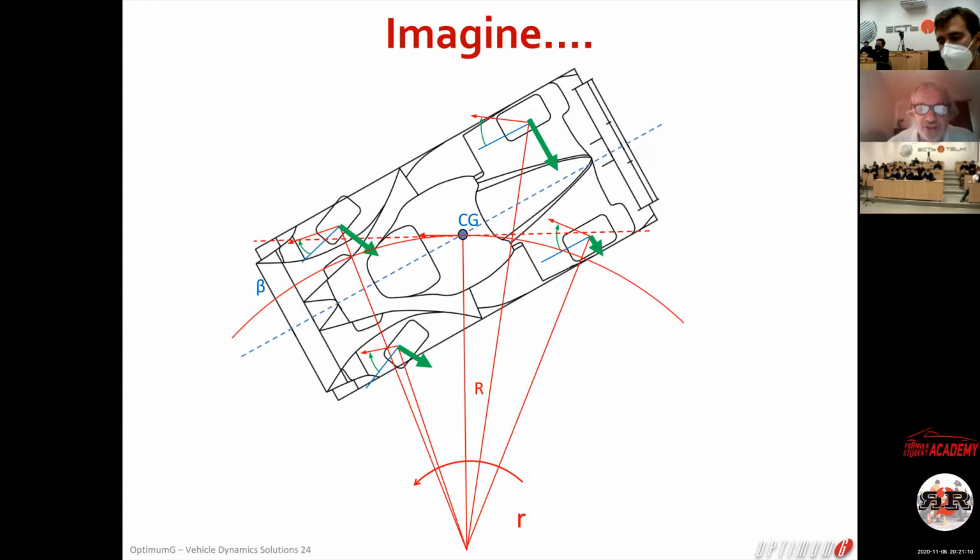So when I change the wheelbase, I change the A and the B, and I change the slip angle. So I change the lateral grip, the total lateral acceleration and the yaw moment. If I change the weight distribution, let's say I move the car's weight forward and backward, I'm going to change all 4 slip angles, and I'm going to change the A and the B. I will change the lateral acceleration. I will change the yaw moment.